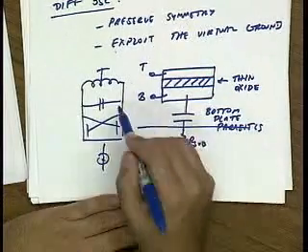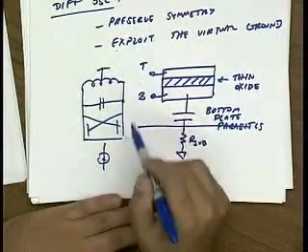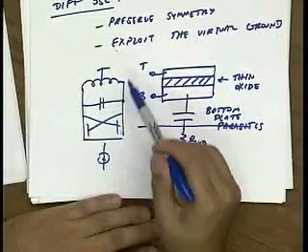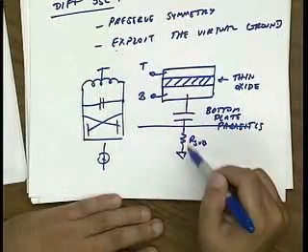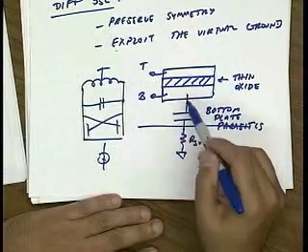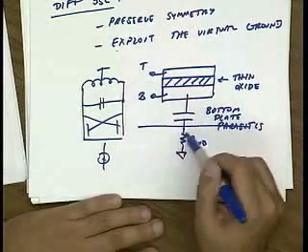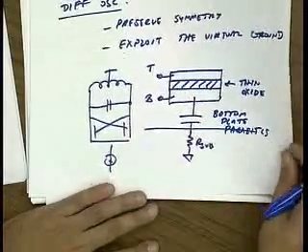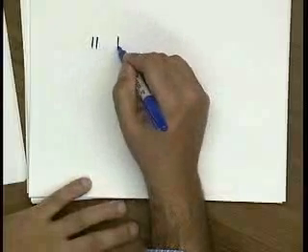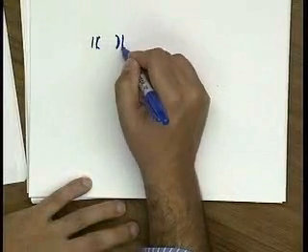Why is this a problem? Where this node can actually swing a very large voltage. You can have on the order of VDD kind of swings at this node. And so the power loss on this bottom plate parasitic, because of the large voltage swing, could substantially degrade the Q of your circuit. Okay? So of course the solution is very simple. Just use two capacitors. I'll draw them like this to emphasize the bottom plate.